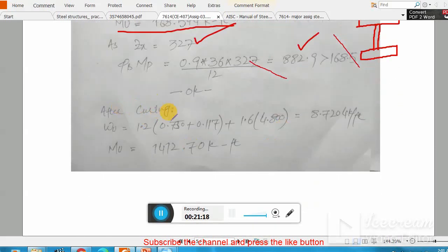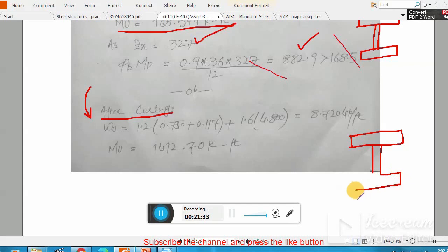Here after the covering, once we come to the second stage, now we are considering the composite section, and the strength of this composite section will now be more than the first one, because once your concrete is covered, it starts its behavior and takes loading. So the moment capacity of this section will be more than this one.